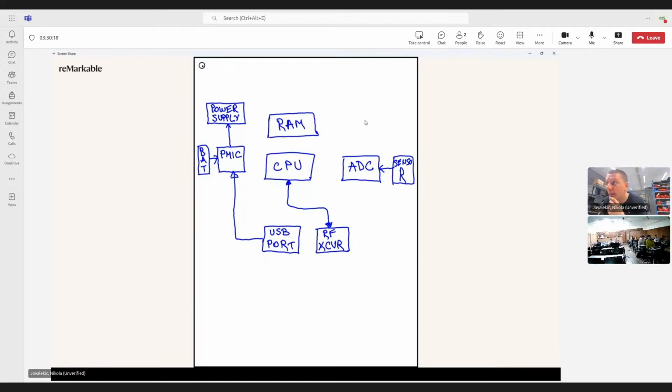A serial bus. Yeah, I mean this is a serial bus, this UART, if we say it like this. That's all we need here. Basically, these components are usually made as modules, so you will have a UART interface. If you just purely use the integrated circuit, you will have something like SPI or I2C. But okay, these are so standard, interfaces used everywhere. When you have PCB communication, then on the PCB you will use one of these interfaces. But let's check what we have here between CPU and ADC.